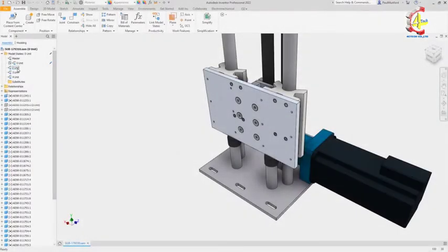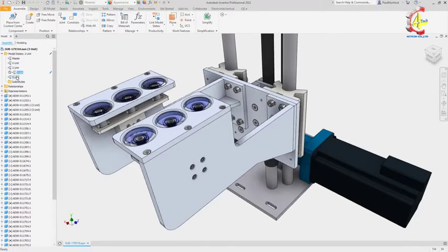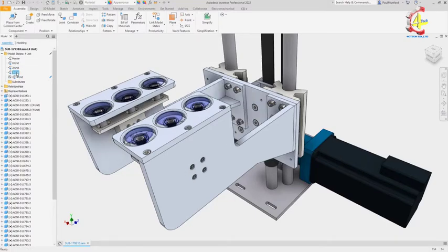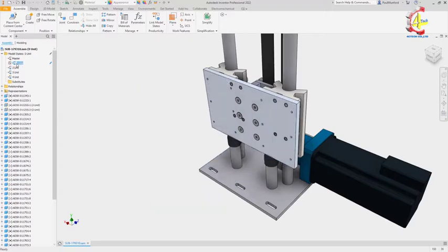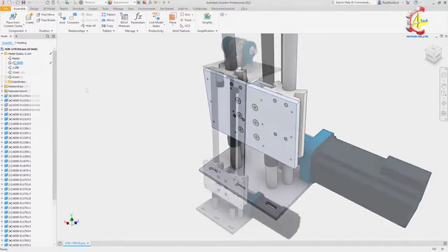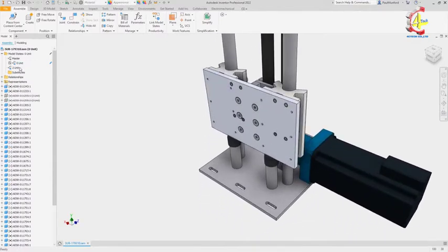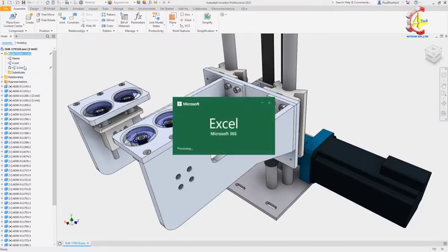Assembly model states inside of Autodesk Inventor 2022 provide new workflows to manage multiple representations of your design. Model states can be used in assembly models to capture your design intent, show multiple manufacturing stages, assembly configurations, or a simplified version of your design inside of one assembly file. In this example, we see a new model state being created. The new model state records the suppression state of components and remembers the model state settings of subcomponents.